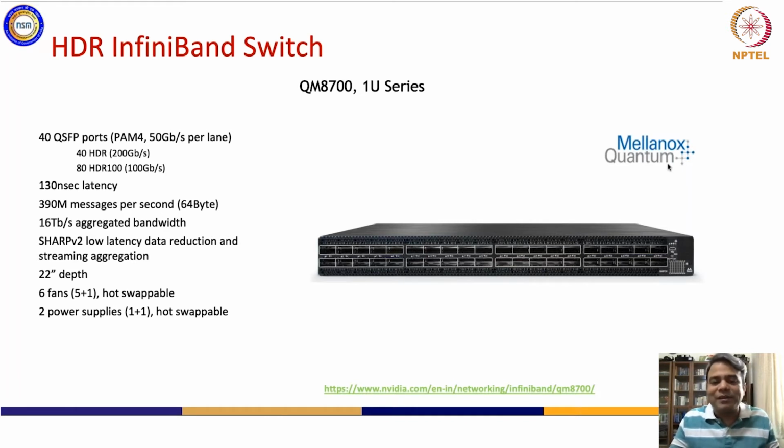You connect a copper cable or an optical transceiver. The transceiver or the copper cable is receiving data from one server. The data comes in at a very high rate. We are looking at, let's say, 200 gigabits per second. The data comes in, and now the silicon needs to decide what to do with the data. So obviously it contains some sort of header. The header contains the source address and the destination address. So the silicon inside this switch is required to look at the destination, and then check from which port it should send that data out so that it will reach its destination.